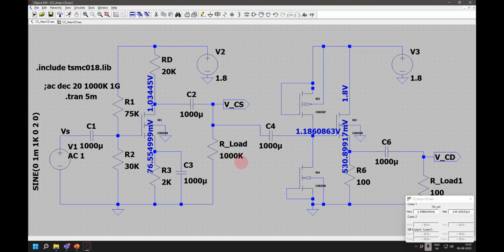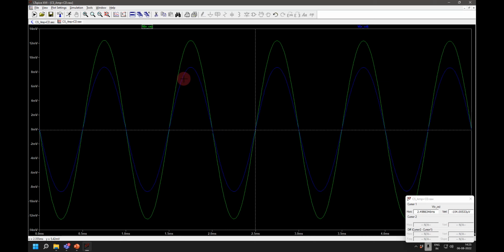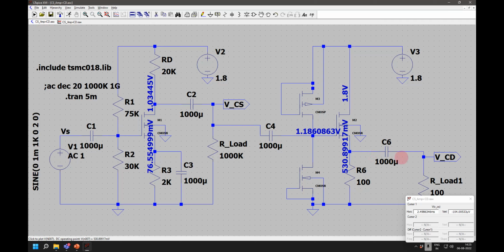When I am putting 1K here instead of 1000K, right? Whereas now I am putting 1000K here, I have introduced one more amplifier in between. Here I am giving even 100, right? So from around 14, it has gone to around 9. Okay, there is some drop from here to here, but still I am able to put 100 ohms resistance. So that is important for me. Is it okay? So if you see any amplifier, the final output stage will be a common drain amplifier, wherever I require. Yeah, tell me.